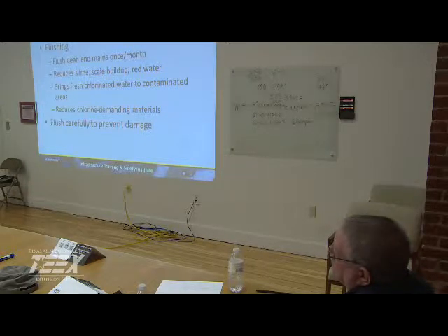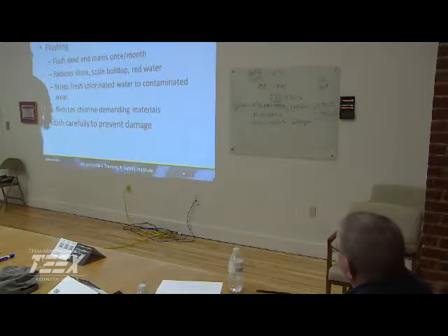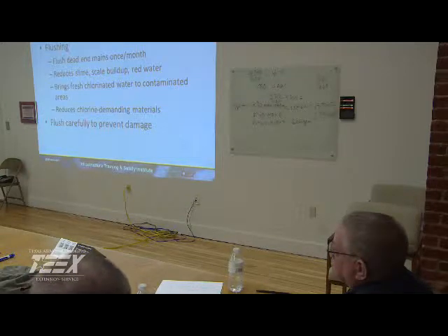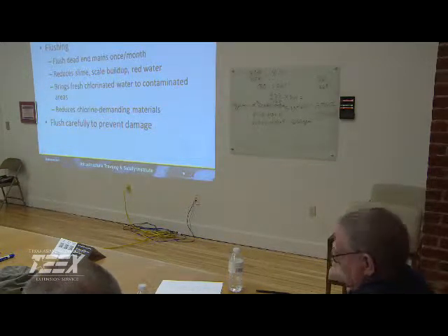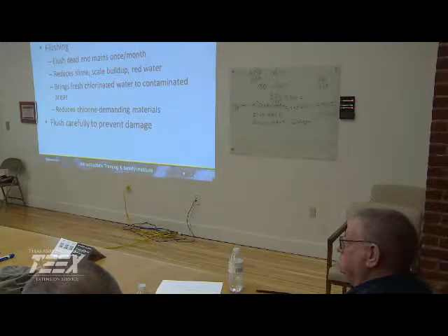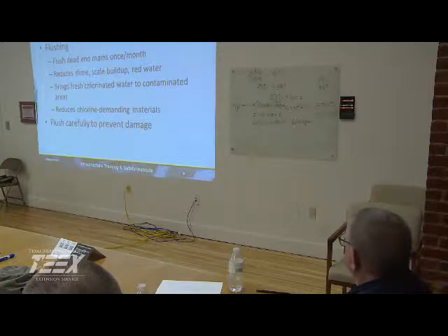You'll notice it's got GPM. And this is made for a 2.5-inch hose connection. So I flush my hydrant a little bit, and I put this on here, and I open it up until I get to 626 gallons per minute. And then I got my little stopwatch, and I time it for 4.4 minutes, 4.5 minutes. And then I know that I have what? Clean that line.